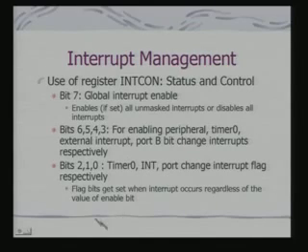In fact, when I enable peripheral interrupt, this corresponds to another set of interrupts, because I can have many peripherals other than those which are listed here. For enabling or disabling those interrupts, I have a different register.